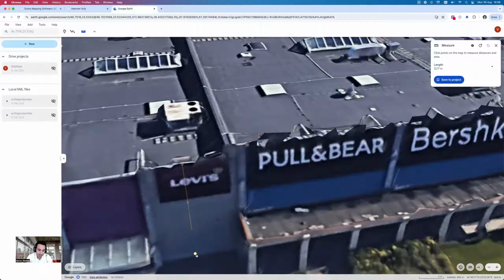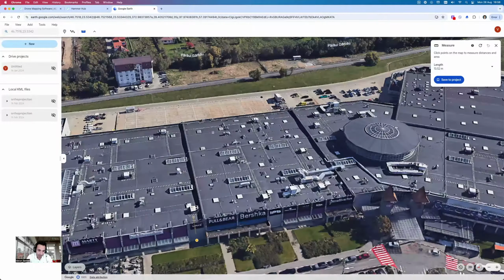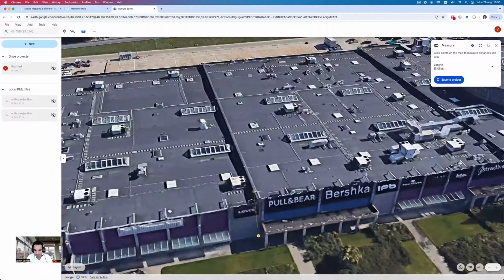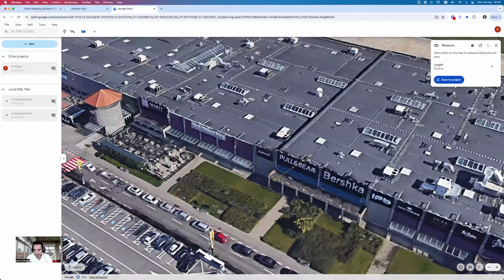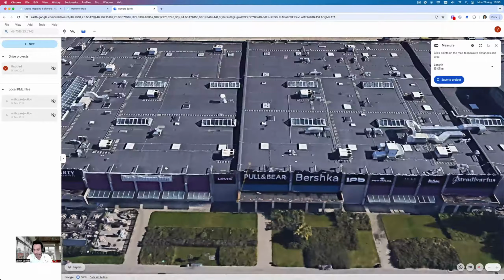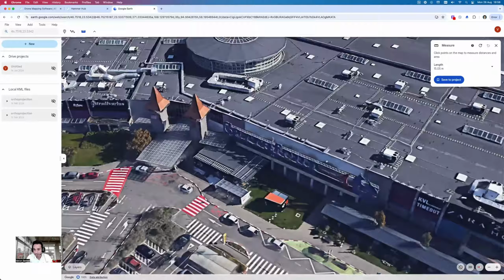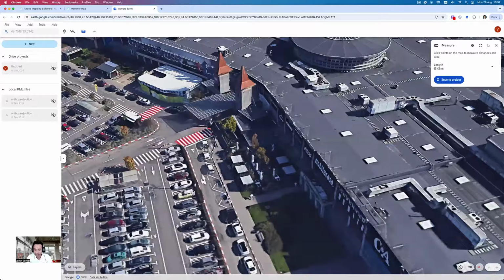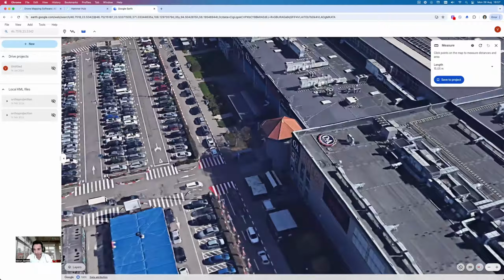So let's say we're gonna drag this out here, and we think the building's at 12 meters. So somewhere between 12 and 13 meters at this point. If we take the higher point over here, we notice it's at 15 meters. And then we can essentially just look at the facade of the building and try to estimate if there's any other point that we haven't looked at that might be higher than that. But assuming that 15 meters was the height at that point that we sampled, and we're looking at the rest of the facade, and we've got this building here, which is actually slightly higher.